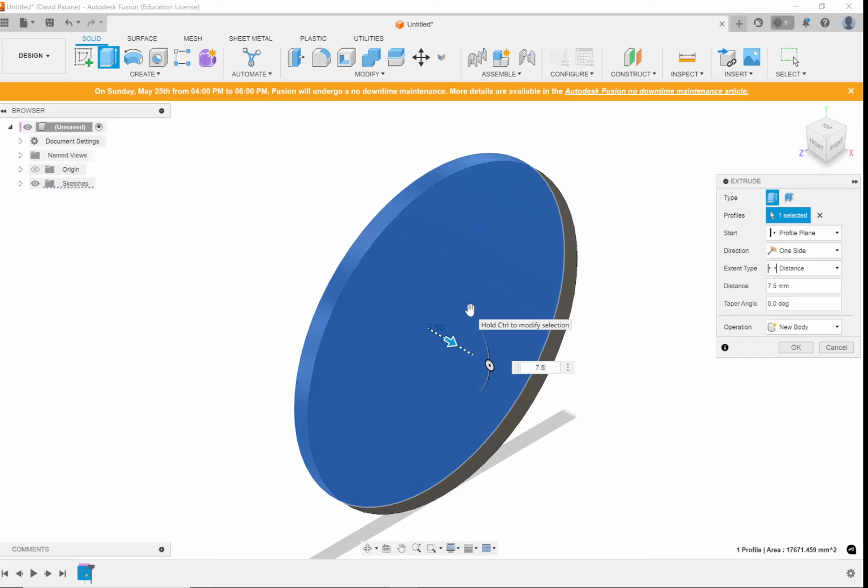I can do that. Some CAD software, like Fusion, allows you to even use formulas. So if I have 10 millimeters, but I want this to be three quarters of 10 millimeters, I can times it by 3/4. And Fusion does, and most CAD software, you can put the equation right in there.